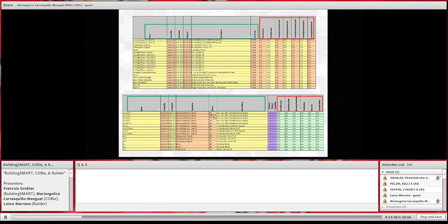Same with the component. The components are the specific instances of each of the types. And each one of them is referenced back, like you have air handler type 1, which is this type. So it's referenced back to the types, and it's referenced back to which space the piece of equipment is in. Again, it has a description, and it has some blank information because it's in the design stage.